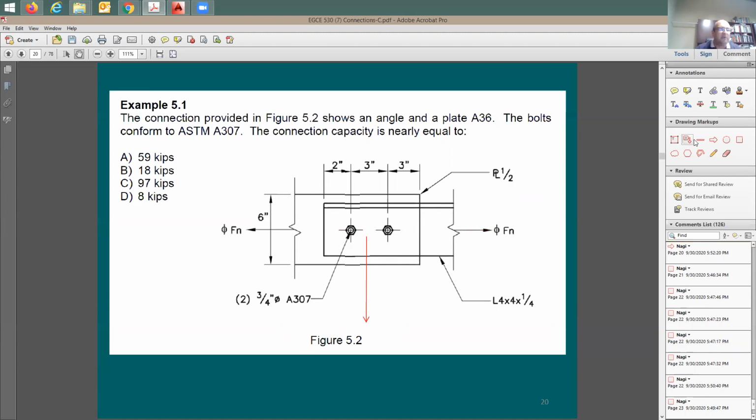Now, where is the center of the bolt? I'm going to say center of the bolt is going to be right here. It's going to be like this, right? If I bring this and put right in the center of the bolt, and also you may call this center of rigidity, if you like. If I bring this here, I'm going to have to split this force equally on these 2 bolts. The problem is going to happen once I start to bring this force right here, like this, for example. If the point of application is here.